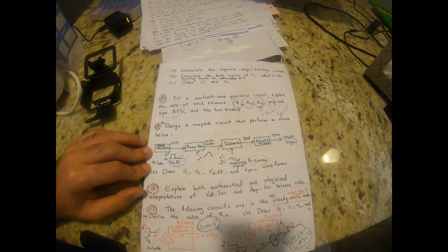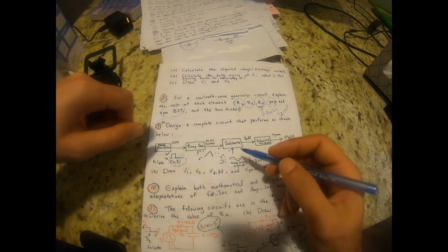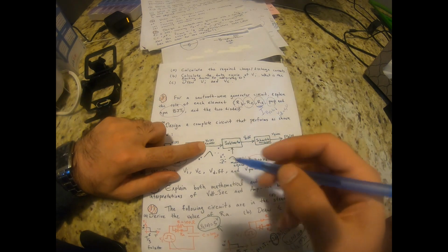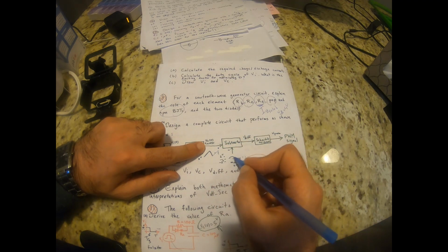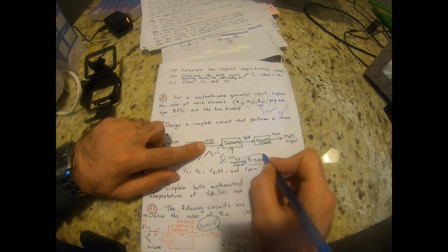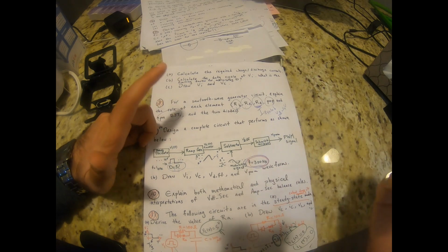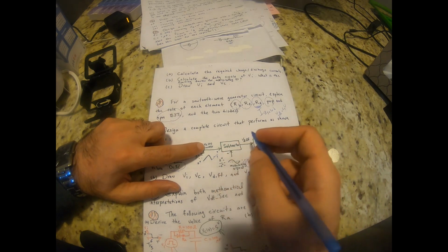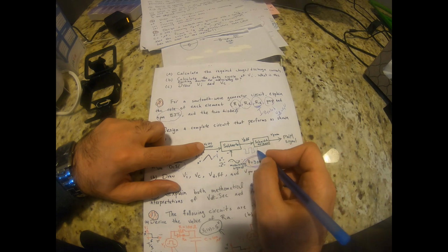You can calculate that. Once you generate your ramp, your sawtooth waveform, you can subtract it from a sine signal using a subtractor. I forgot to give you the frequency of this one. You can make it equal to 300 hertz, but any value you want to use doesn't matter. I just wanted you to subtract this so that you end up with a signal like that.